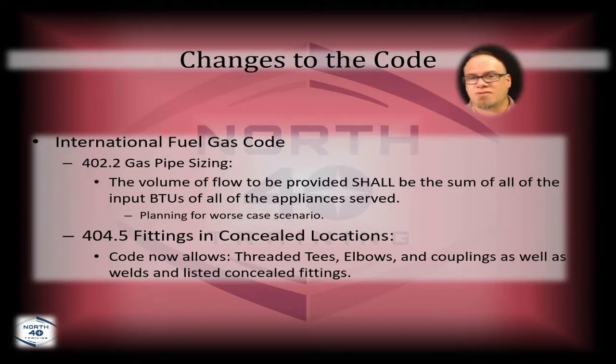So what happens if you've got that, and that's all you've got available for the house, or maybe more than half of it, but you haven't served your furnace yet, you haven't served your stove, maybe you've got a fireplace in there? Those things have to be taken into consideration as well. So make sure that you're doing your sizing properly, and if you don't have enough, fix it.